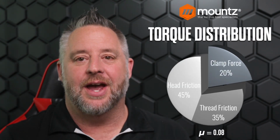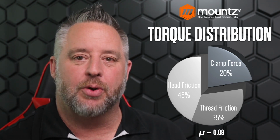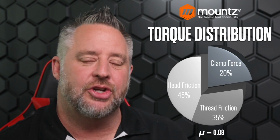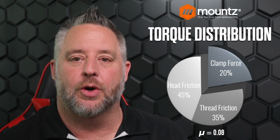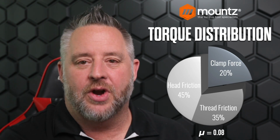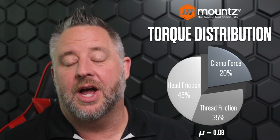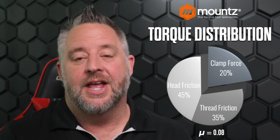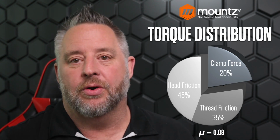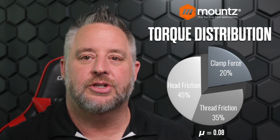Now, the distribution of the torque that we are looking at that's happening during the actual installation and assembly process has a breakdown of this. And so if we're looking at a coefficient of friction of 0.08, we are seeing 45% of the frictional forces come from the head bearing surface, 35% from the thread friction, and then there is about 20% that is going to the actual clamp force or the actual stretching of the fastener to create the overall clamp force that we're trying to achieve.